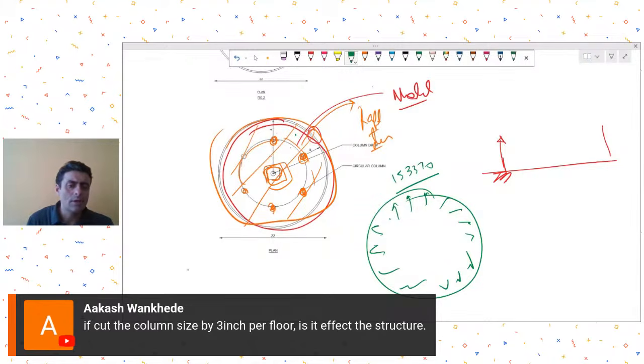And then in a second model, where you just want to design your top slab, you model the wall, you model all the columns, apply the load on top slab, and then see what is the requirement for column, beams, etc. And then take that model to your raft and then do the raft also over there. Okay. All right.